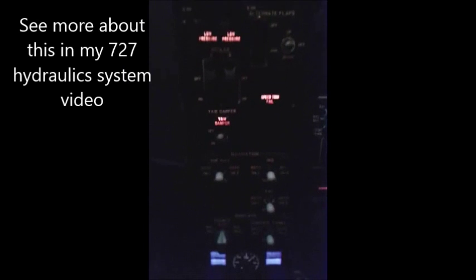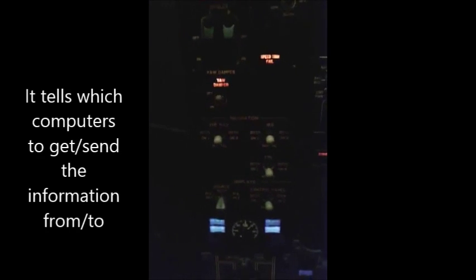More electrical panel, that's where the battery and different meters can be given. And over here, we have a flight controls panel where you can activate standby systems or not. A navigation panel, you can select both on 1 or 2 depending on the failure. Source displays, and then the fuel panel. And then all these knobs right over here and switches at the end are the exterior lights. That is the 737NG overhead.